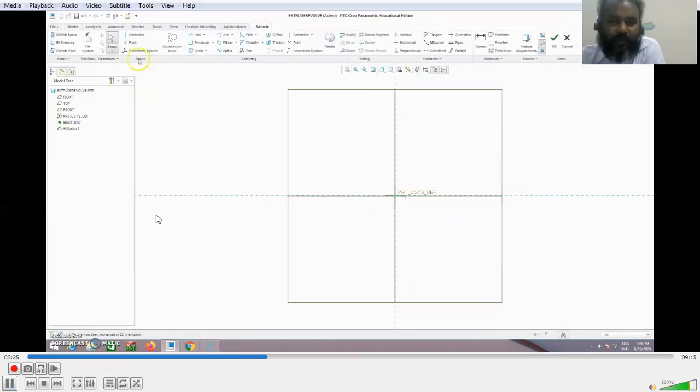And what we are going to do is, under the datum umbrella, so if you see here, this is the datum umbrella, and I'm going to pick the center line option from the datum umbrella. So using this feature, I'm going to draw the center line at any point I want. It need not be matching the, say, y-axis in this plane. You can as well have a center line anywhere. So here, center line is drawn here, and then I'm picking the line option. I'm just drawing a straight line of a particular dimension. I'm just changing the dimension to the required size.